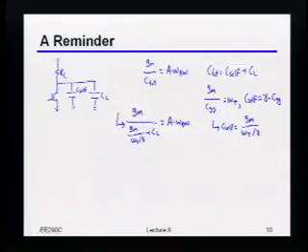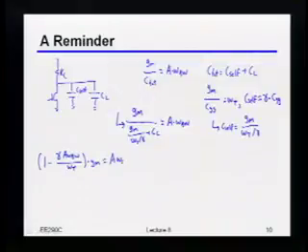So from here, I'm just going to rearrange the terms a little bit. I'm just going to group all the GMs together. If you do that, then you get something like (1 minus gamma times A omega bandwidth over omega t) times GM is equal to A omega bandwidth times the actual explicit load cap. By the way, all I really did there was pull this up to the front and subtract it off onto the other side, and then regroup it in terms of GM.